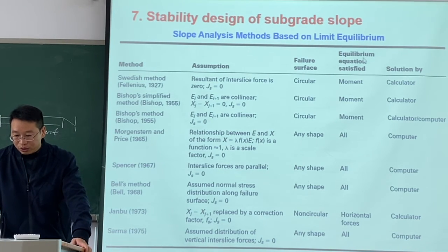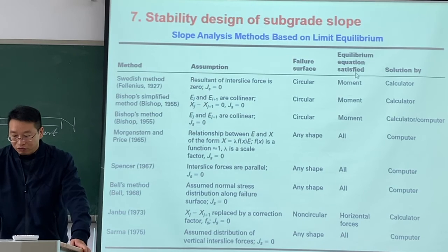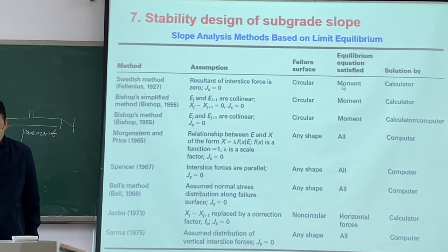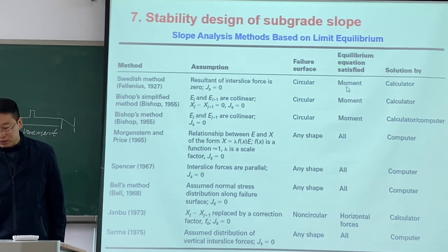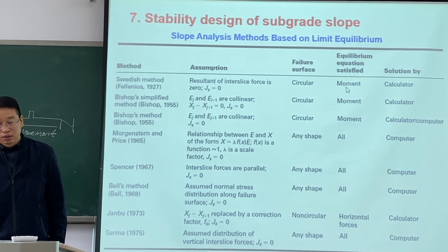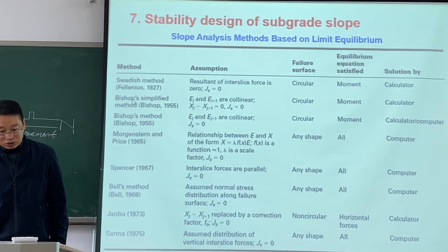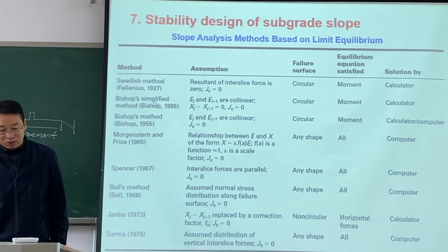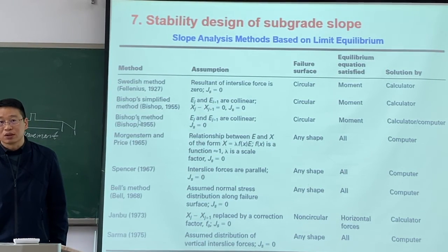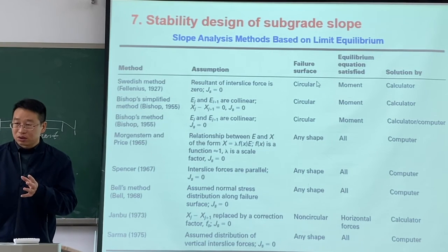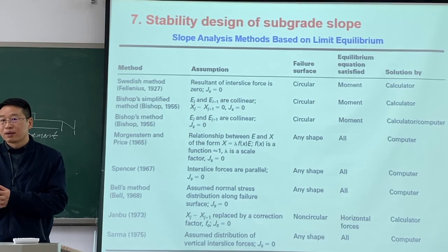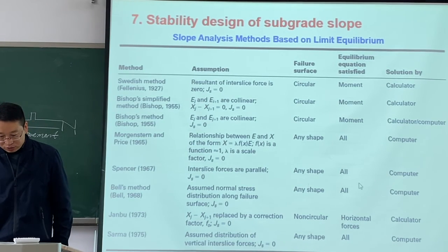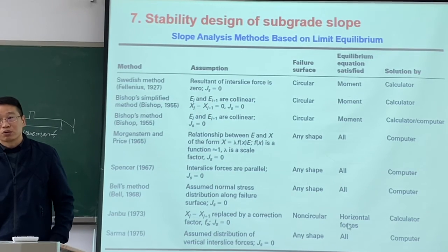And the equilibrium equations satisfied are different. For the Swedish method and Bishop's simplified method, it only considers moment equilibrium. But for Janbu, it is horizontal force equilibrium.